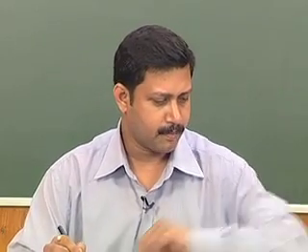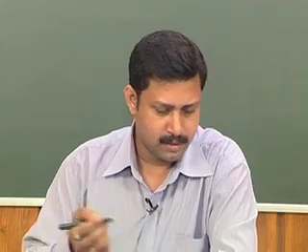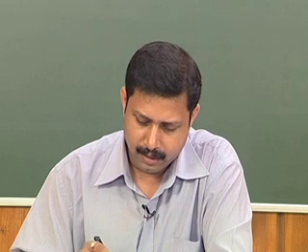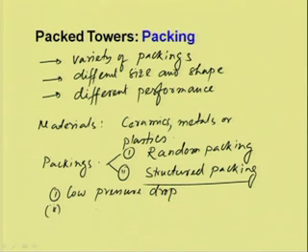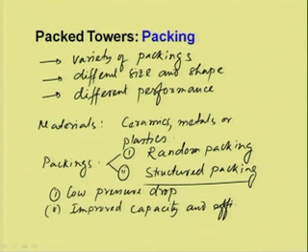In the case of structured packing, different varieties are available, and the advantages of structured packing are, first, low pressure drop, and second, improved capacity and efficiency.